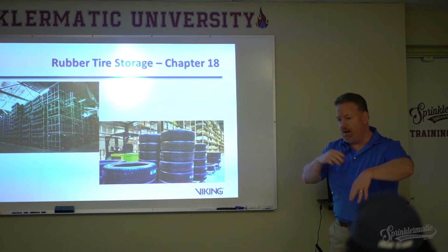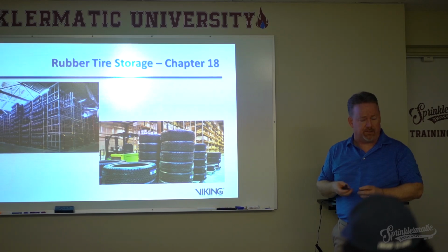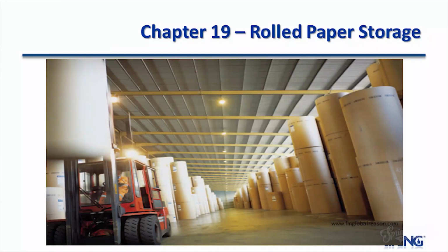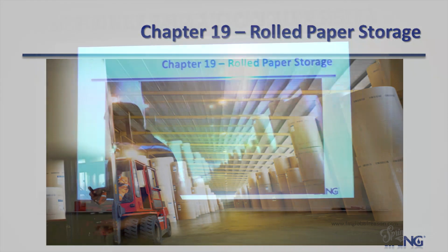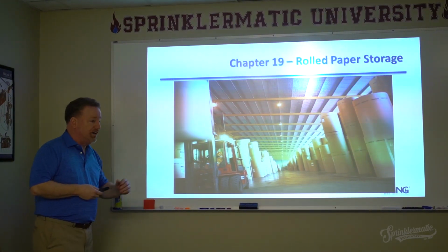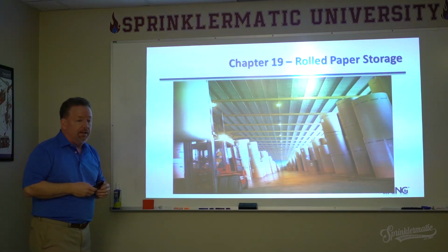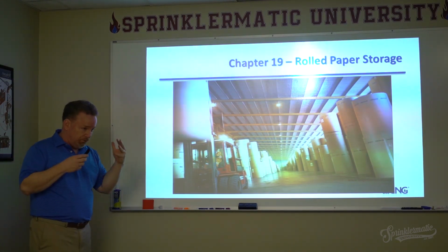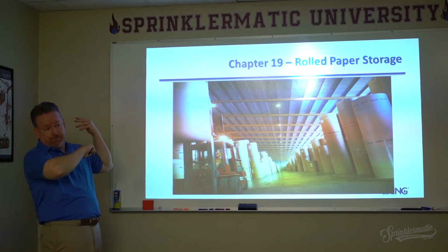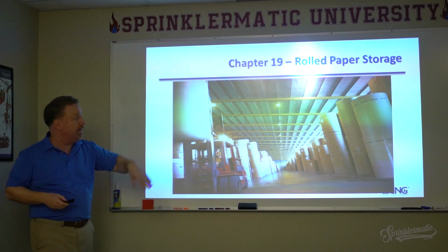Now you've got a lot of air going around. You get a fire started here. It's a big challenge. Chapter 18. Chapter 19 addresses rolled paper storage. This chapter in and of itself has not changed much at all over time. But basically, if you're protecting a rolled paper storage warehouse area, you don't use Chapter 16, 15, 14, whatever it is. You go right here to Chapter 19.